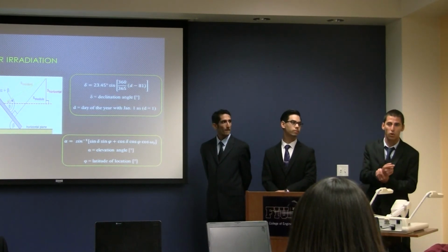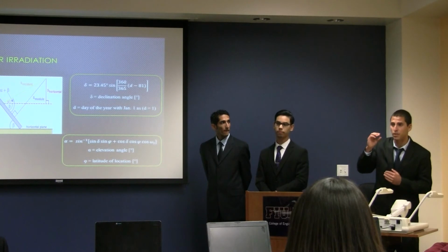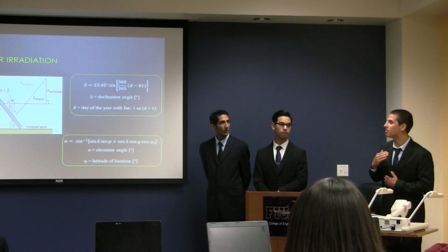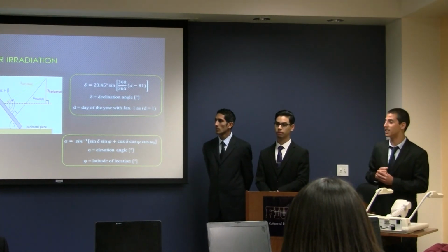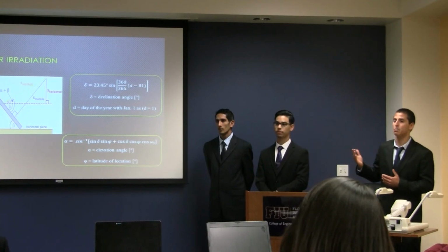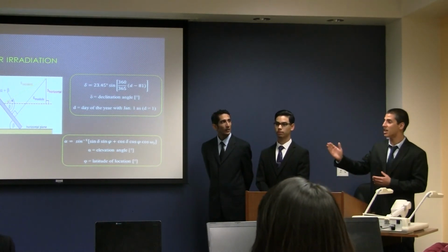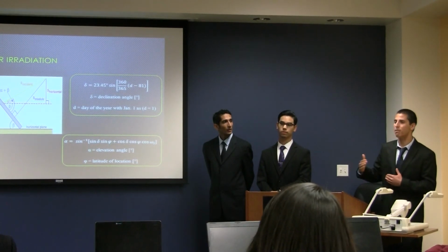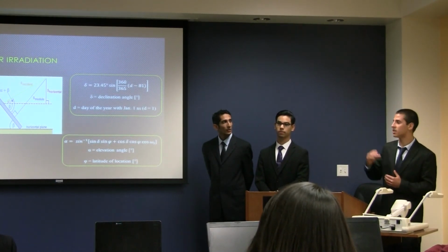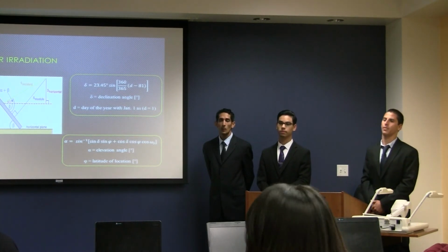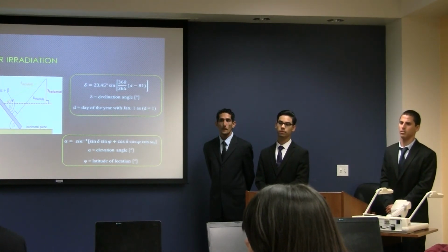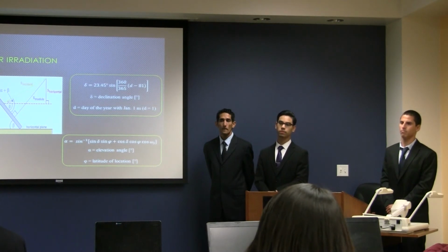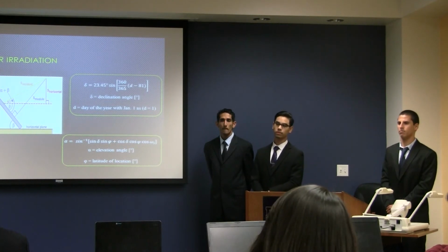Like he mentioned before, how the graphs, the flat panel should have been closer to the curved panel at midday. We believe because of the cell manufacturing deficiencies, like we explained, some resistances in some of the cells are greater than others because each one is not perfectly manufactured. So that will give us a greater resistance, and obviously in the flat panel, this is why it did not compare to the curved panel at midday. Okay, so let me ask you this question. How do you compare flat panel output to curved panel output and make statements about curvature being the improvement if all things other than it are held constant?